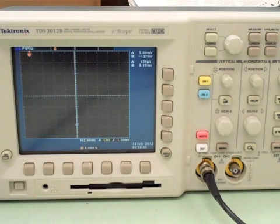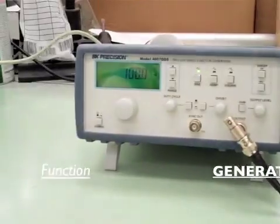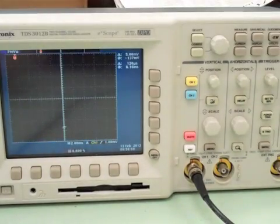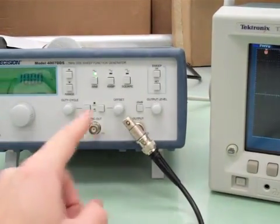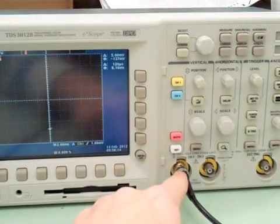Alright nerds, today we're going to learn how to use a digital oscilloscope and a function generator. So first, we're going to start with this guy. We're going to need to send a signal to it, and we'll get to that in just a bit, but basically we're just going to take the BNC out of the function generator and put it into position 1 here